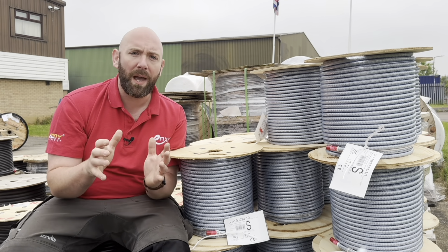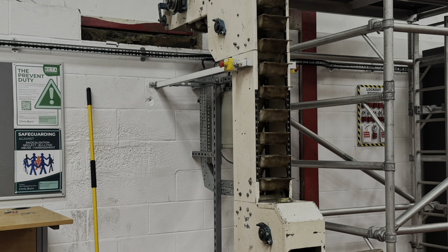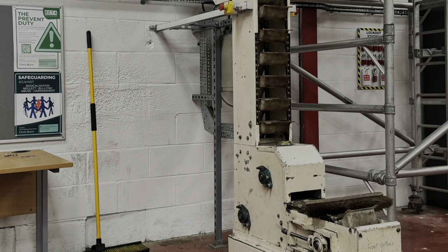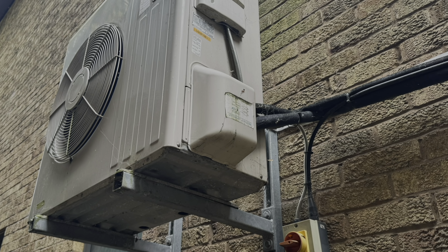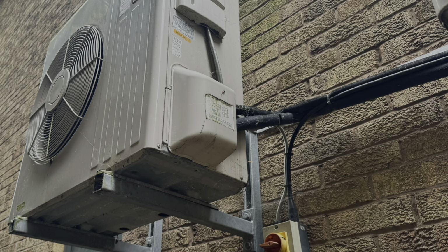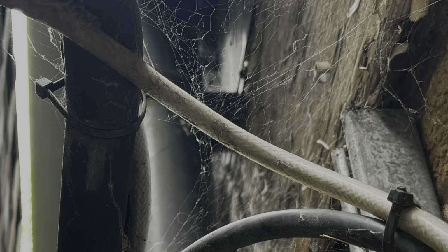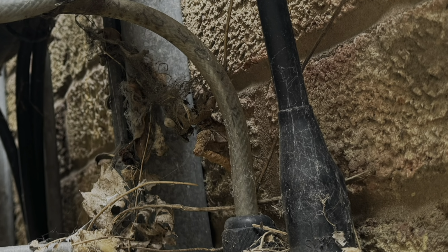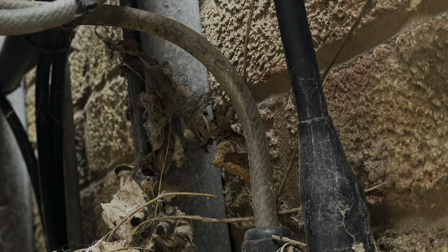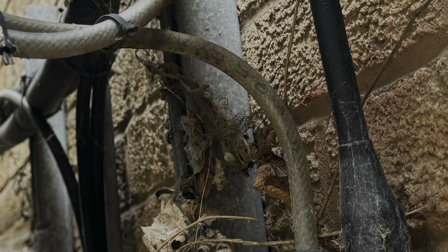So what should SY be used for? Well, it's a control cable which should send signals to equipment like conveyors, elevators, assembly lines, and for where I always used to see it, air conditioning units, so the internal unit could talk with the external unit. But what is clear about SY is it should not be used outdoors or for installations that need to meet the requirements of BS 7671. And as we can see from these examples, when installed outside, they can let in water and be damaged very quickly by UV radiation, causing the insulation to go brittle and degrade.